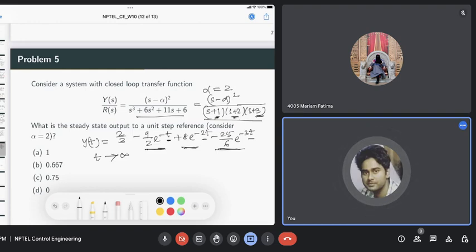So we are only left with y(t), value 3. For t at a very high value, it is equal to this. So this is the steady state output of the system. For this system, when we give this unit step input, the response will be like this, and the steady state will be after all this transient response has died out, that is, when t goes to a very high value, all these terms will decay. So we are only left with this first term, and that will give the steady state response, right?